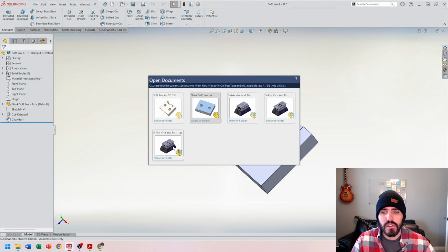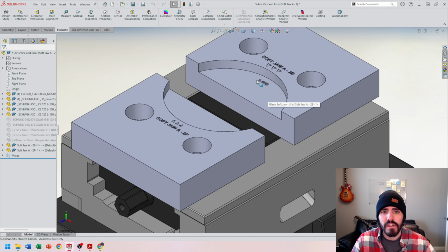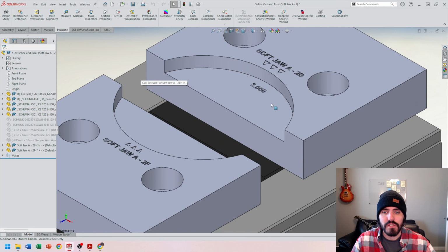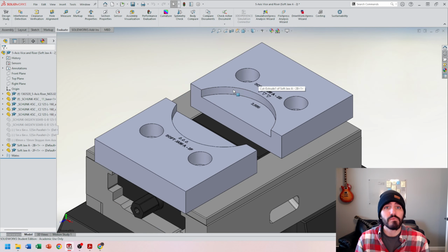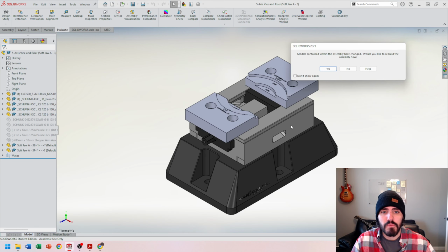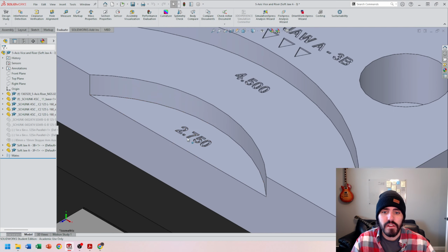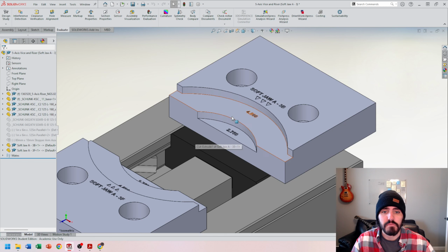So if I go over here to this assembly, you'll notice that I have a 3-inch round diameter that I'm holding, a 3-inch round stock piece of material, because I wouldn't be able to hold it in a square hard draw. And then likewise, I have a double step where I have a 4.5 and then a 2 3/4 diameter piece that is being held.